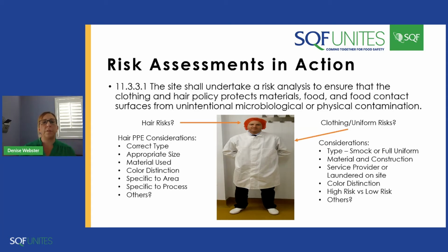Why did you put those things into place? How did you go about considering it? Why are there color distinctions or no pockets above the waist? Well, we know that we're preventing potential unintentional microbial or physical contamination from entering the product stream. So when you're doing your risk analysis for your clothing and hair policy, which must be documented for compliance, factor in those two elements, the hair considerations as well as your uniform.